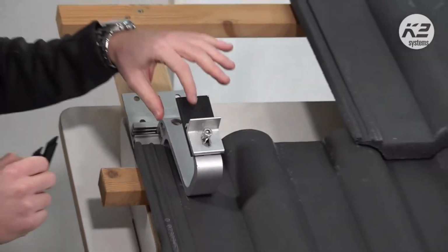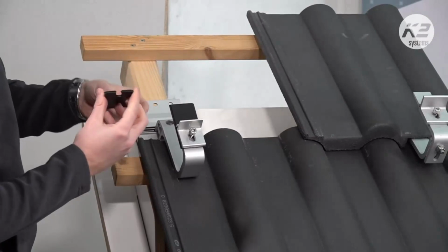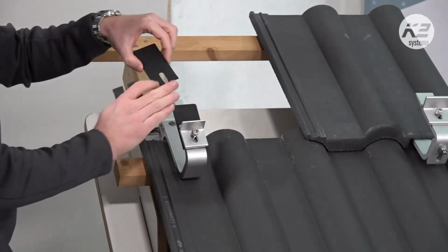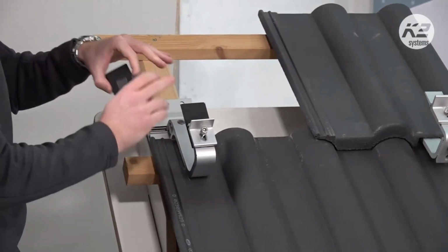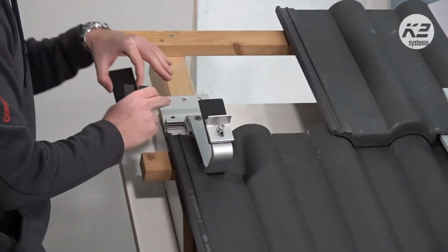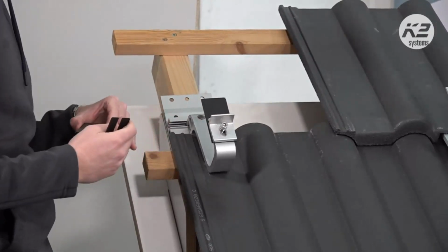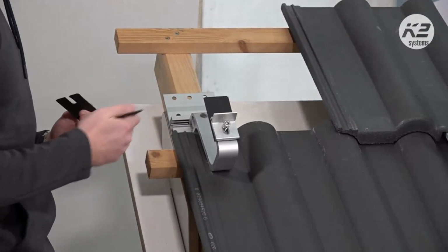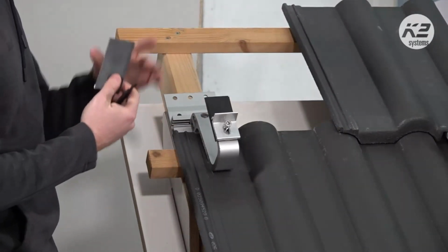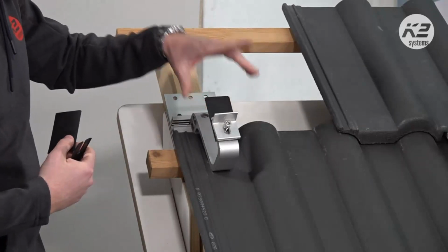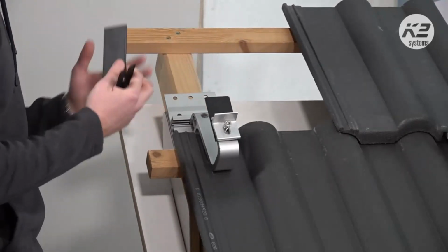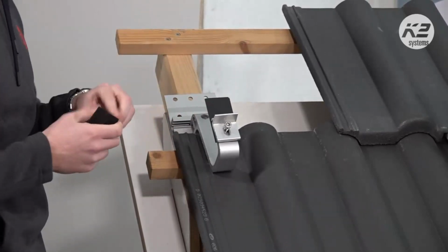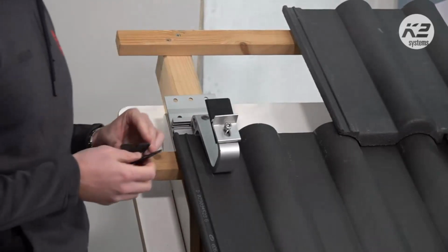And what if I wanted to increase it more from here? Here we have the ability to install two distance pads on top of each other. So we'll have 4 millimeters total. So we have this ability here to install double, but here we install only a single part. So as I said, depending on the necessity in the project, whether I need 2 millimeters extra height here or 4 millimeters here, I will choose either the distance pad or the height compensator.